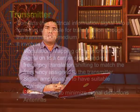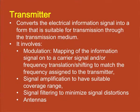The transmitter's job is to convert the electrical information signal obtained from the output of the input transducer into a form that is suitable for transmission through the physical media. The transmitter can involve certain signal processing operations including modulation, which is mapping of the information signal onto a carrier, and or frequency translation or shifting to match the frequency assigned to the transmitter. Another job could be signal amplification to have suitable coverage.